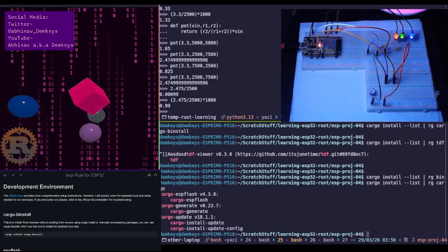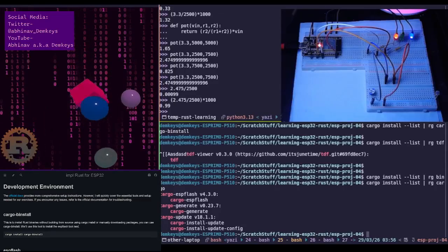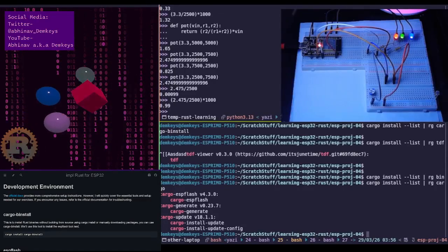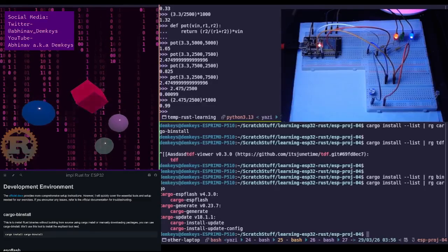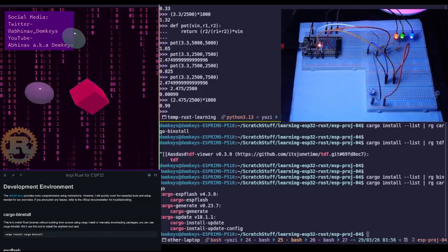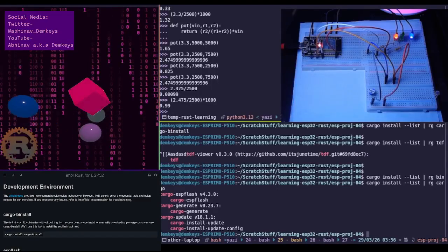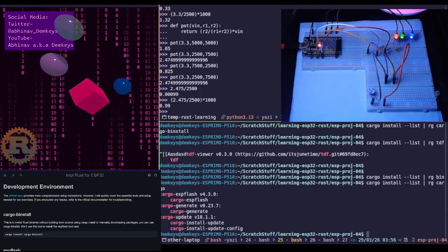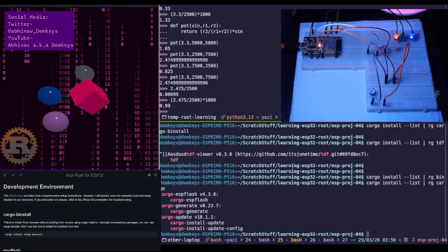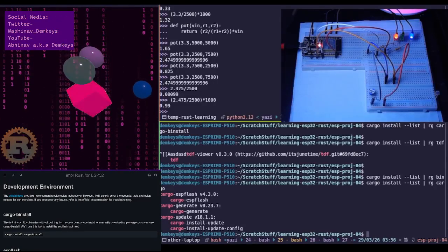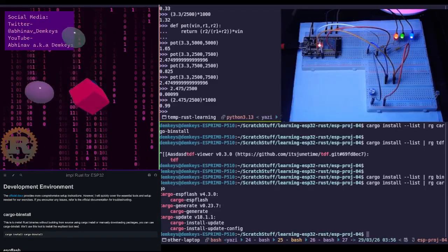But yeah, if you are setting up a circuit like this, a lot of times people will recommend setting up a flyback diode, and I'm guessing this is also one of those situations. This is making me think that it is in fact a solenoid, because I'd been told that these relay modules also have opto isolators, optocouplers in them. But I think that might be for a different part of the circuit, because you wouldn't be using an opto in a situation where high current was involved. They're not meant for that purpose.